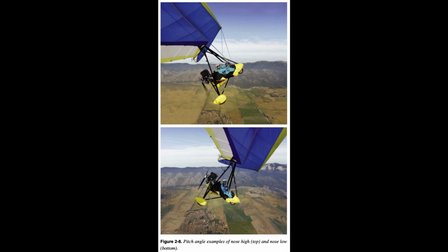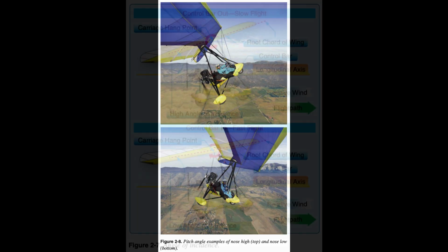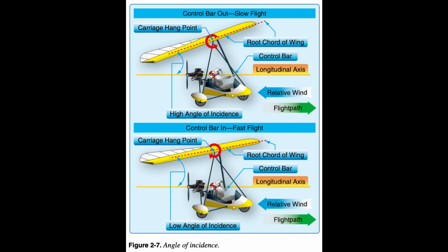It is parallel to and opposite the WSC flight path. Relative wind may be affected by movement of the WSC through the air, as well as by all forms of unstable, disturbed air such as wind shear, thermals, and turbulence. End of page 2-4. When a WSC is flying through undisturbed air, the relative wind is parallel to and opposite the flight path. Figure 2.7.